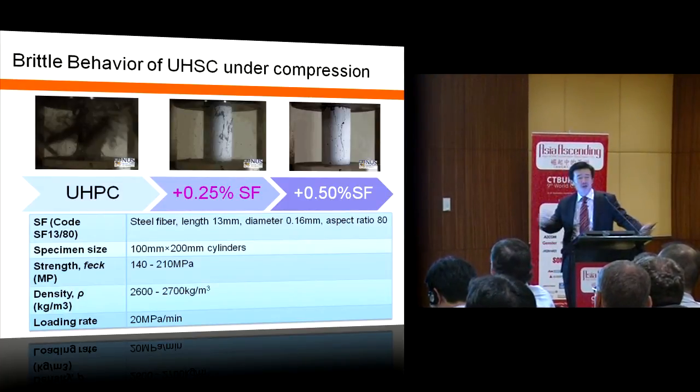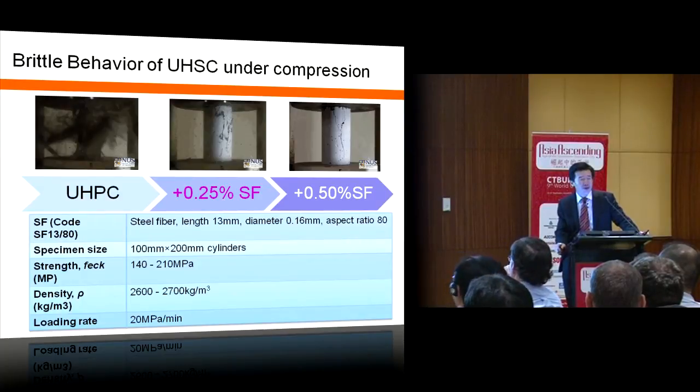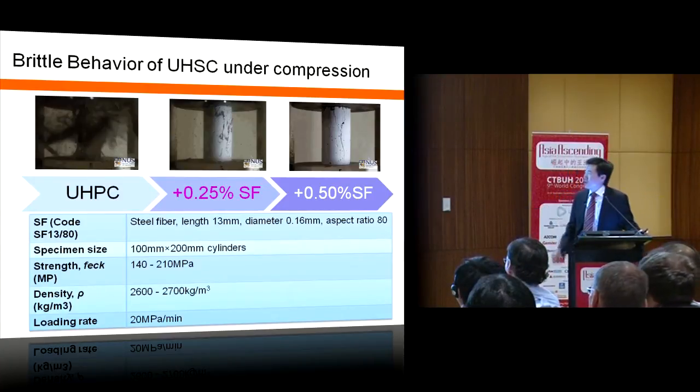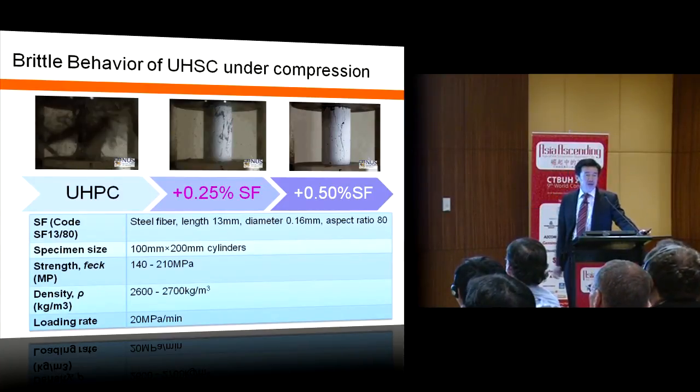That means suddenly there's an explosion. You cannot get any unloading path. So can you imagine if you want to use this style of concrete in your high-rise building? Do not overload it. If you overload it, the column disappears. All this load has to shed to the adjacent columns. So how to improve the ductility of this column?